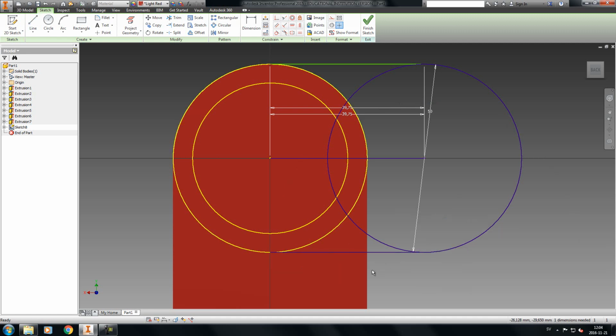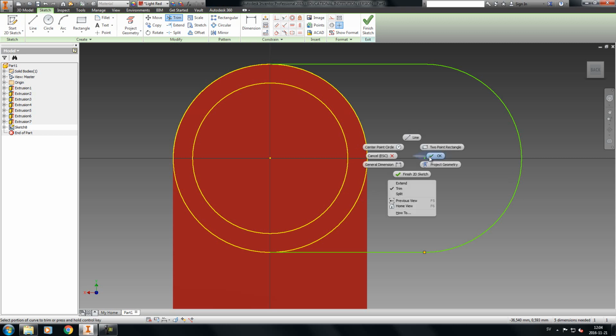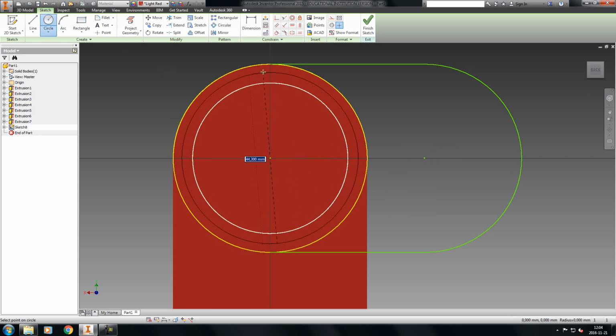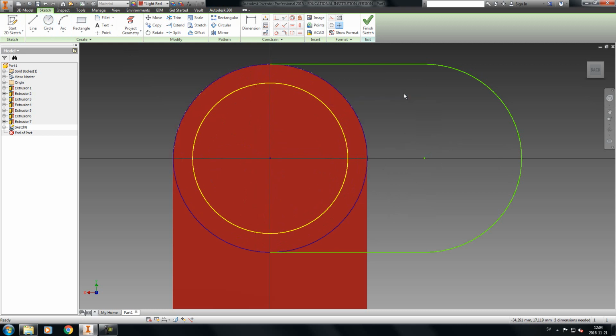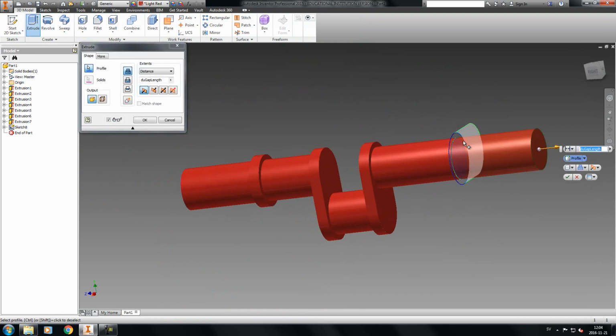Press left click. OK. Then choose all of the different dimensions. Choose trim. Trim away the parts I'm indicating. Right click. And press OK. Then choose circle again and draw out a 50mm circle there so that we have that. And then choose finish sketch. Then we extrude the entirety of that disk to disk thickness. Du disk thickness. Or, well, yeah, disk thickness.